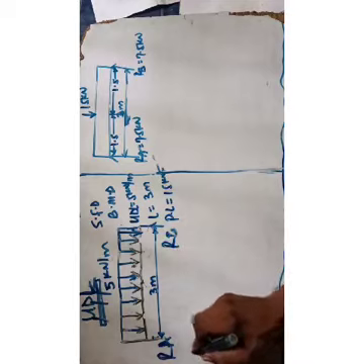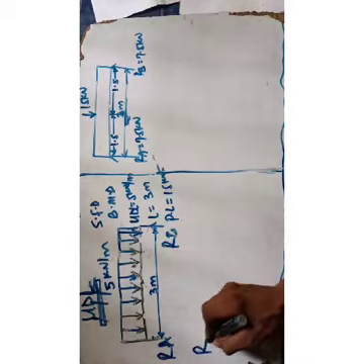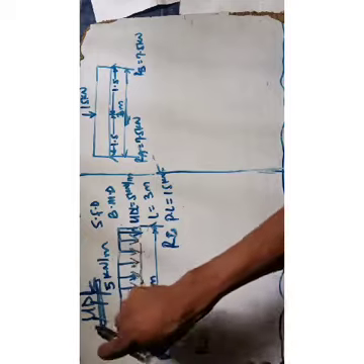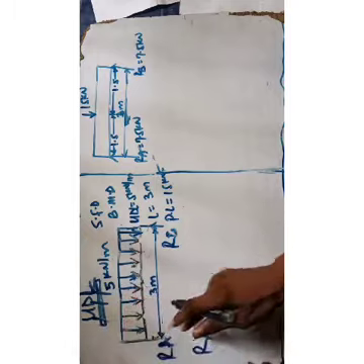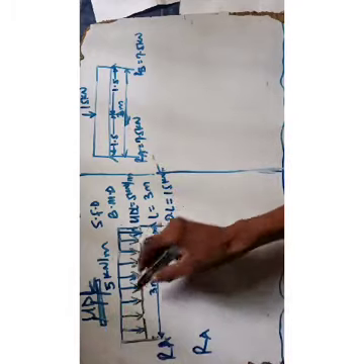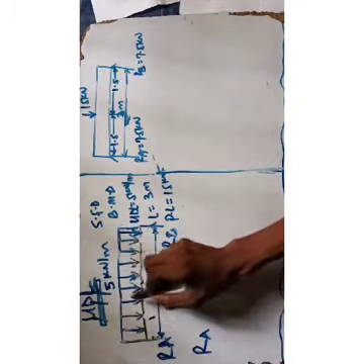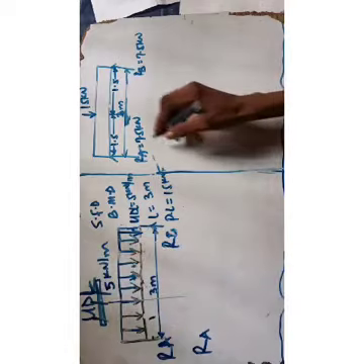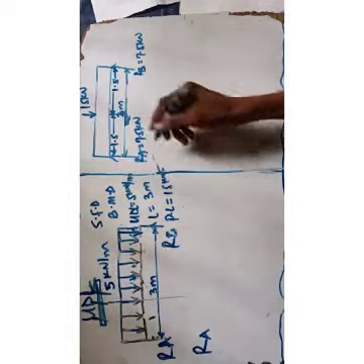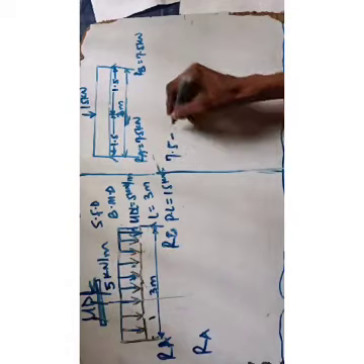That will be your Ra. You remember, you consider the force Ra at x equals 0. That will be this force minus, let's say we want to start when it is 1 meter. Normally, if you want to find the shear force for this, that will just be 7.5 minus what? 15.